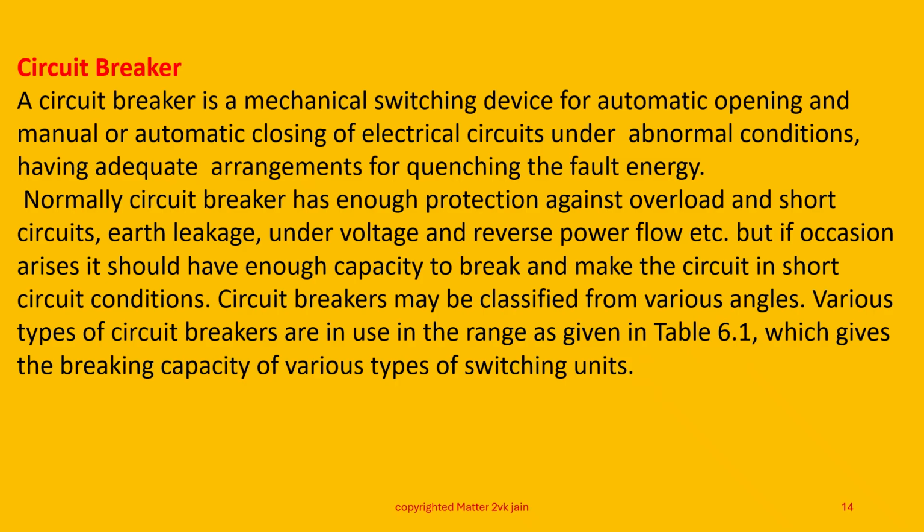Friends, I had been talking about the word circuit breaker. Let us define it. A circuit breaker is a mechanical switching device for automatic opening and manual or automatic closing of electrical circuits under abnormal conditions, having an adequate arrangement for quenching the fault energy. When the contacts come out, they create an arc which has a high amount of energy, so that energy has to be quenched.